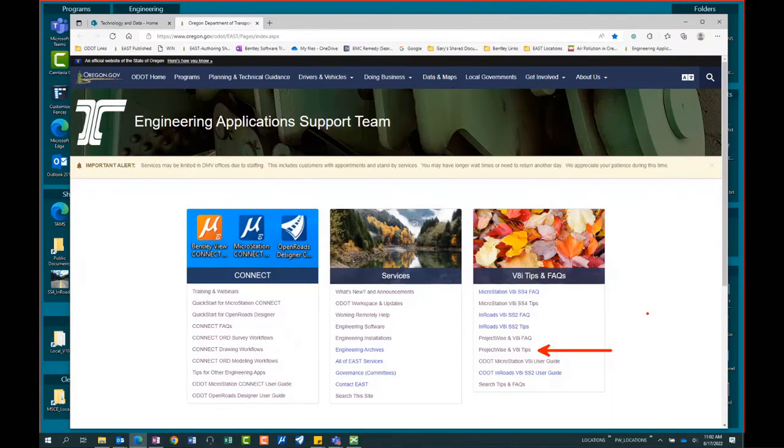I'm going to show you a little additional thing about how to import a small number of project files that all have reference attachments that were made external. And I'll show you how you can quickly import those, use a function in ProjectWise to relink up all your files. Then you can rename them using the naming tool. I'll show you some stuff about the naming tool. And I will also show you which folders they ultimately end up going in, and we'll verify that those links are still good. The main topic is about printing and PDFing.